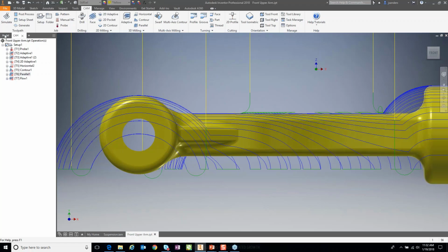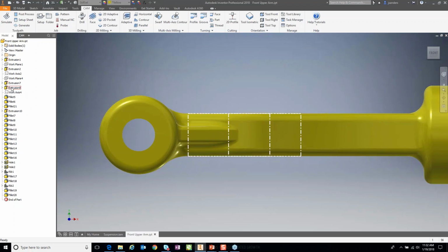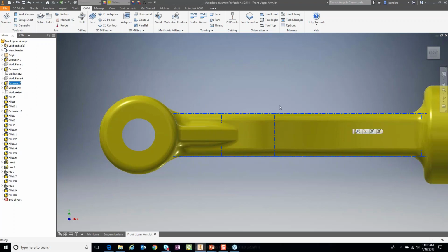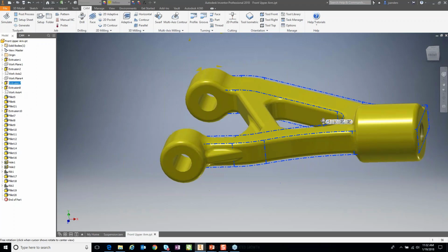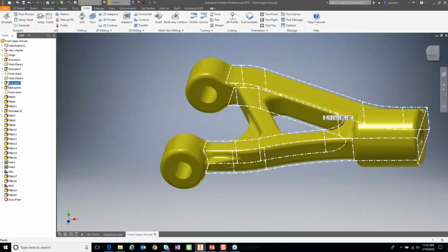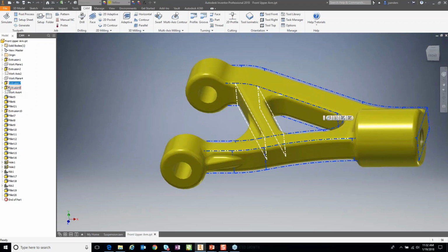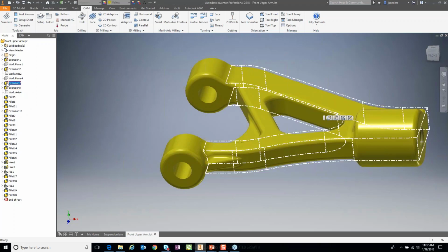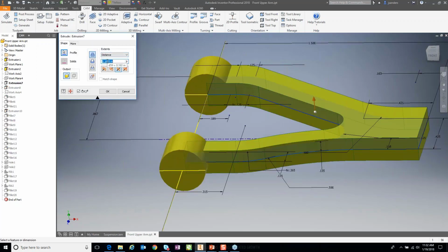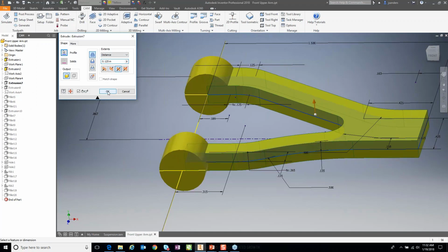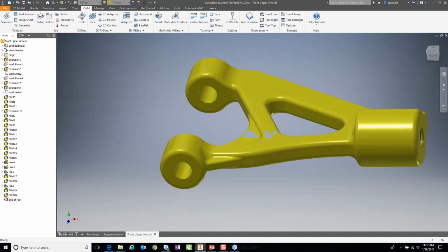When I go out to the model side and I go find the extrusion that builds the main web across here, so that's an extrusion built to a thickness, then there's a spar that comes across here that's to the same thickness. It's driving off the same dimension. So because of how this is modeled, I'll be able to go edit the feature. We can thin this up from 162 thousandths to 125 thousandths. The spar will thin up as well, the cross brace across here. Everything falls into place.